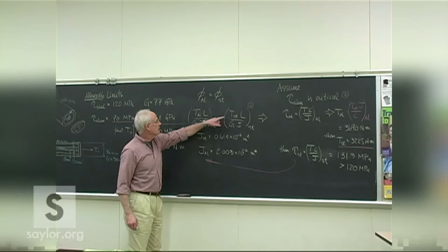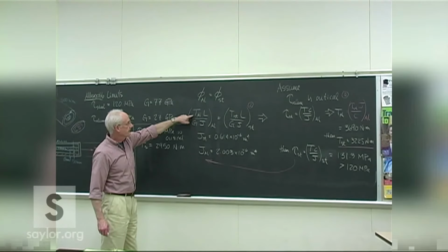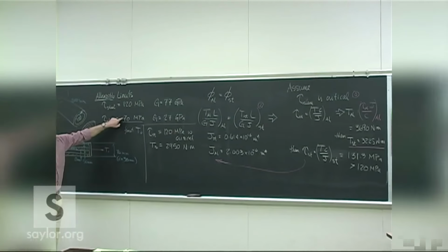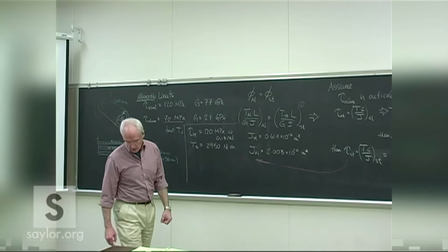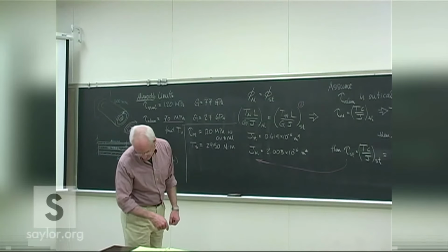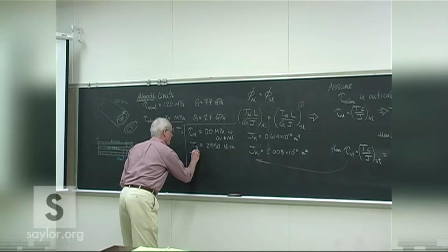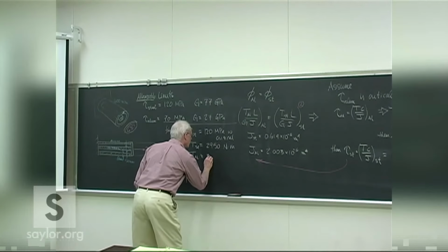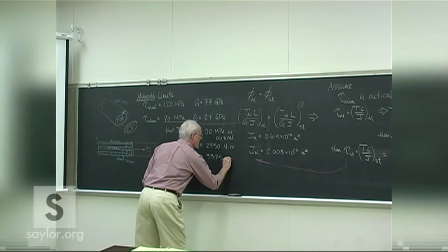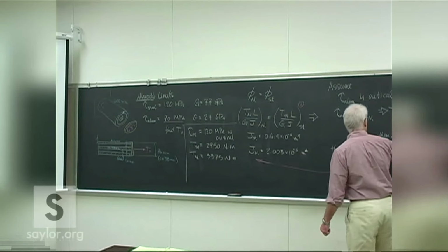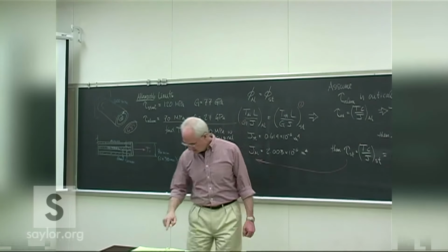Then back into equation 2 to find the load in the aluminum, and then determine the shear stress in the aluminum. And we already know it'll be below this because we reduced the entire load since we first found the steel was the limiting number. So the torsion in the aluminum then is 3375, which we know is less because we had been at 3690 with our original assumption.